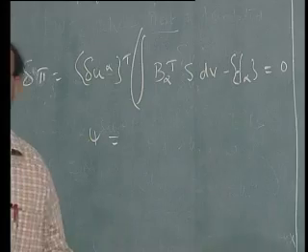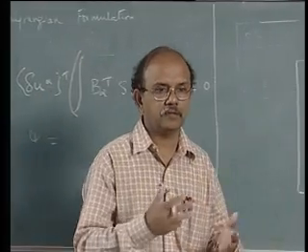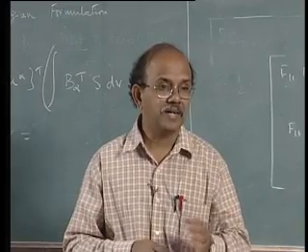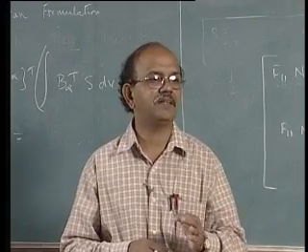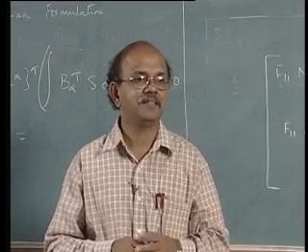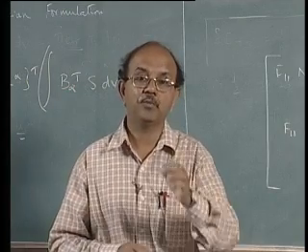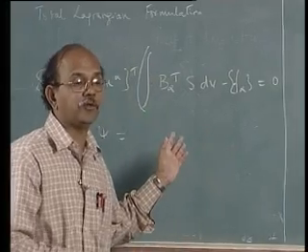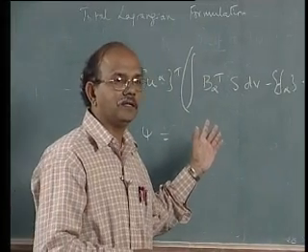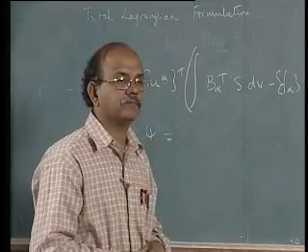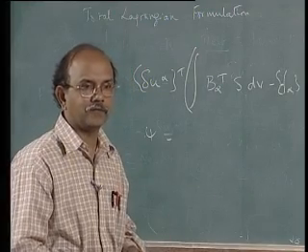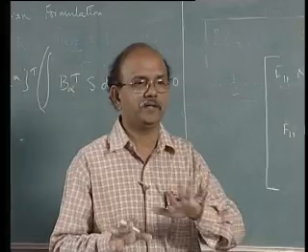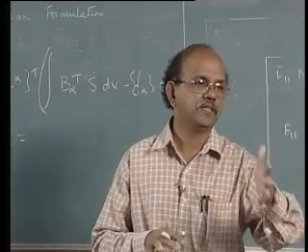Remember that we had put this as B transpose, dou sigma by dou epsilon and so on. But right now, I can't write that next step in the same simple fashion as before. Because if you had noticed in my last session, when I wrote the Newton-Raphson scheme, B was well behaved, a nice guy. It was independent of U.